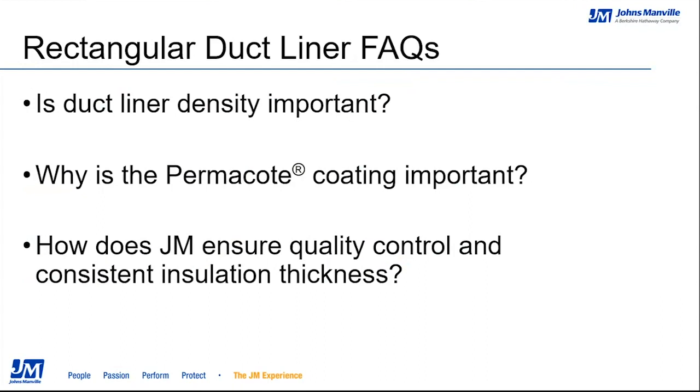The performance-based ASTM C1071 removed the guesswork from the selection of the duct liner system and allowed you, as the engineer or the contractor or even the building owner, the freedom to focus on the duct liner performance itself rather than the density. Meaning you could write a spec based around an NRC acoustical performance need, a thermal performance need, corrosive potentials, fiber erosion and resistance, surface burning characteristics, and other key critical performance things. So what's really interesting is, hey Brennan, you're telling me that this was changed in 1986. Why do we still see these come through?